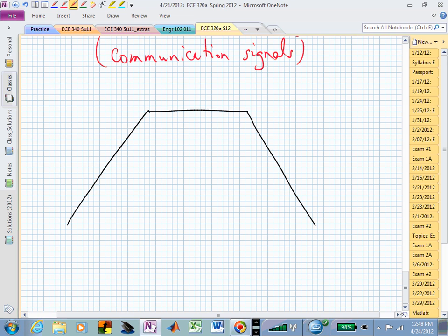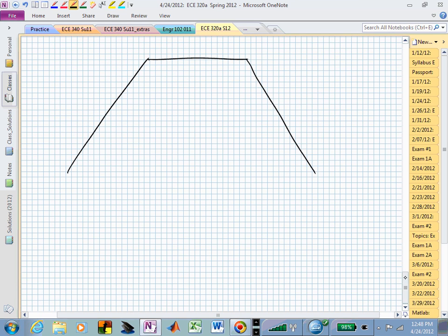And what do we see there? Well, we see a couple of breaks, don't we? So we know we have to have more than one frequency in the denominator. And just one way of realizing that is by means of an RLC circuit.